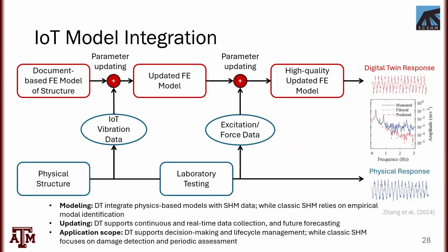And this is really how SHM for digital twin will be different than classical SHM. So we have this continuous integration of real time. It's supporting future predictions. It's improving life cycle management. And you can think about it as a feedback loop where the digital twin keeps getting updated and it keeps providing us with a continuous stream of data.